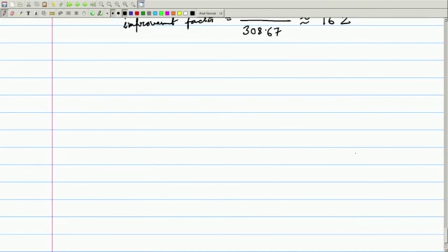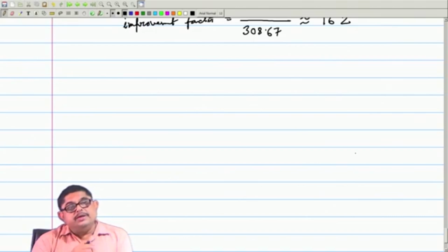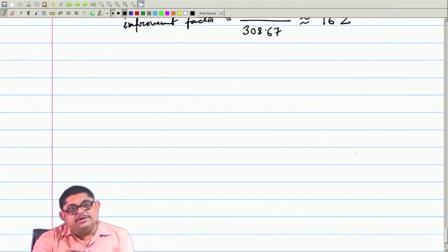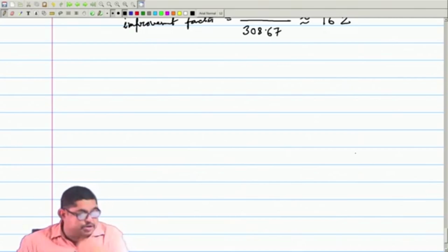So, it is beneficial, but there is another technique that we will discuss next, where by more processing you can have any order of improvement in this frequency domain. And actually this is a cross range case, because generally the range is called down range. In the cross range domain there will be Doppler processing, but this frequency one by integration is generally sufficient for getting a good resolution.